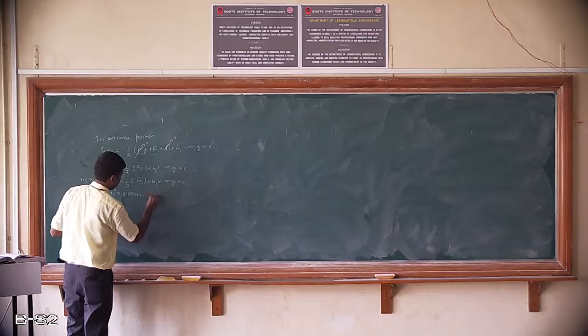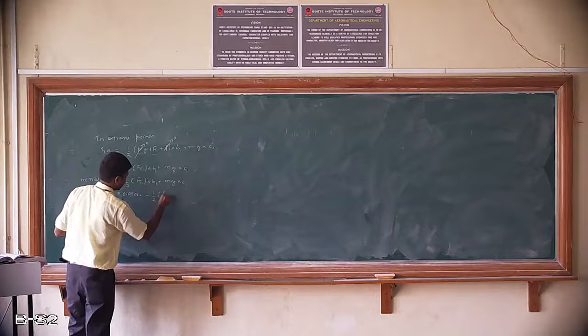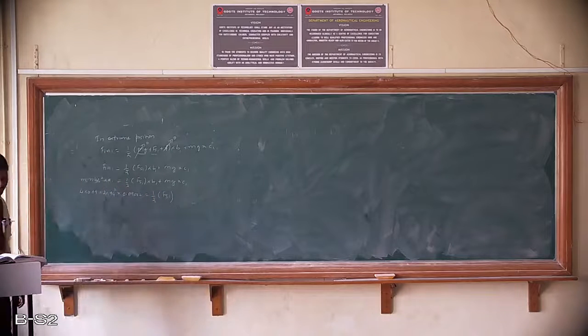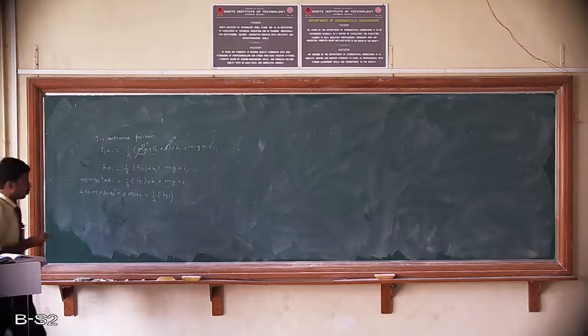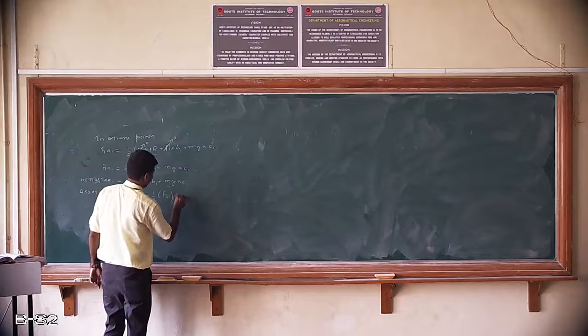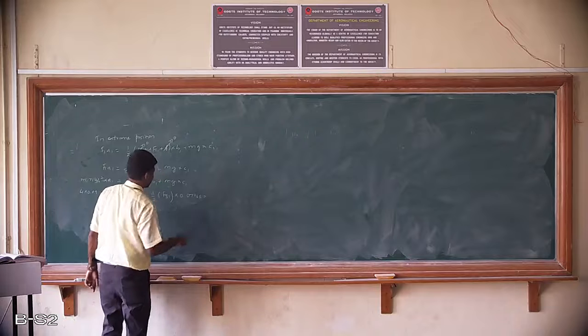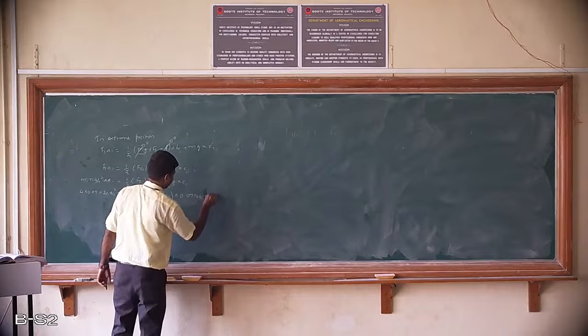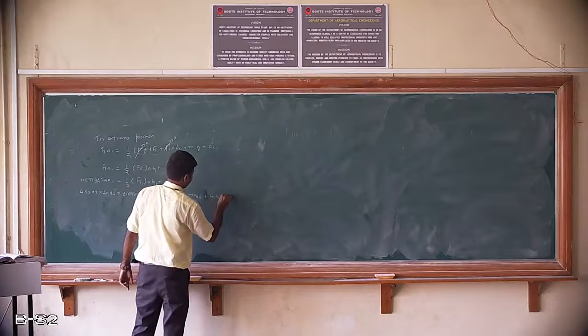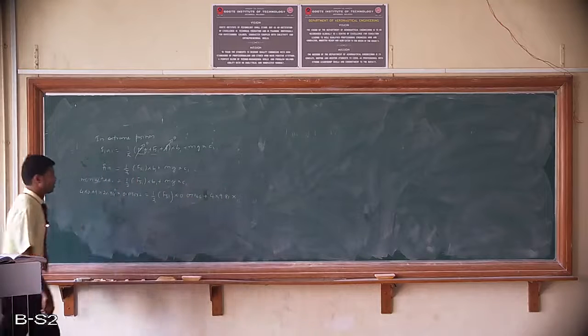So it is 0.09682 is equal to 1 by 2 into Fs1, which I need to calculate, into the value of B. So B1 is equal to B2, which is 77.46 mm. It should be in terms of meters, 0.07746 meters, plus mass of the ball 4 into acceleration due to gravity 9.81 into the value of C1.